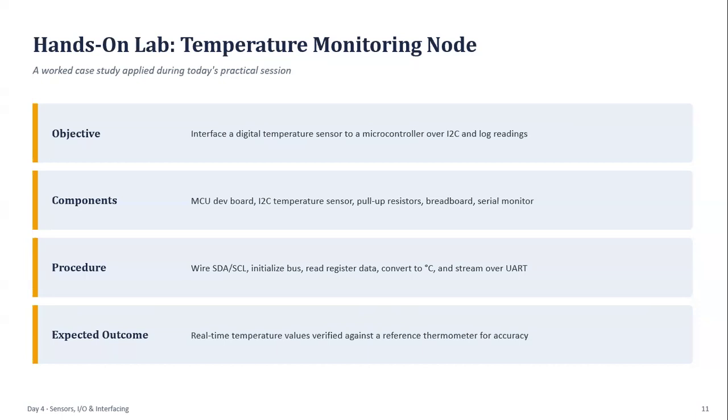You will also wire the sensor, initialize the communication protocol standards, read the temperature values, convert them into degrees Celsius, and transmit the data through the universal asynchronous receiver transmitter module. Finally, the measured temperature will be verified using a reference thermometer to evaluate the measurement accuracy.